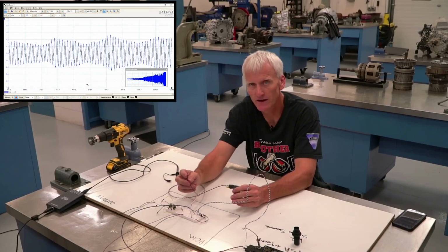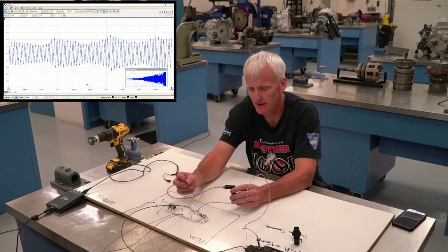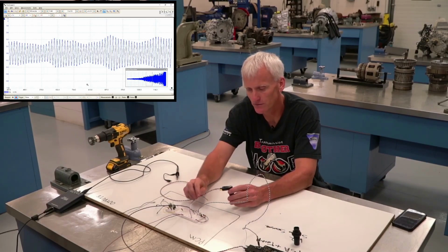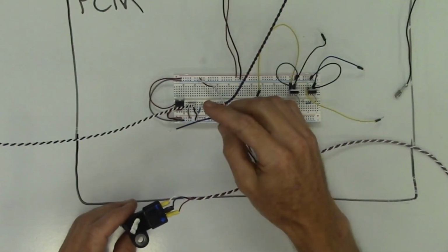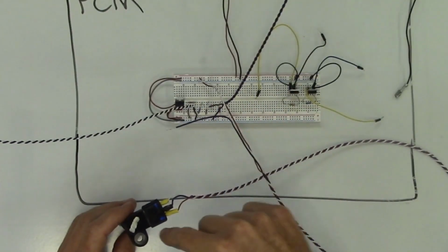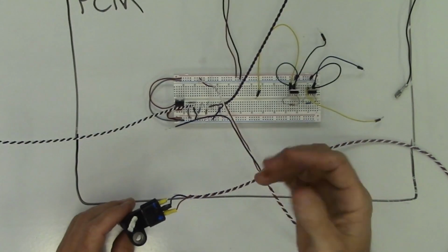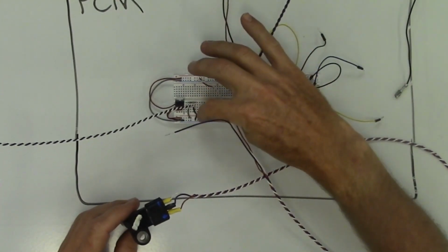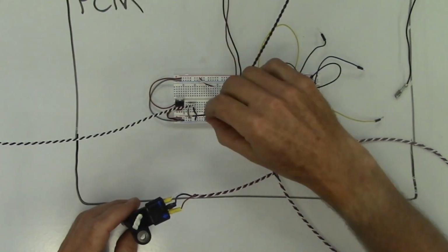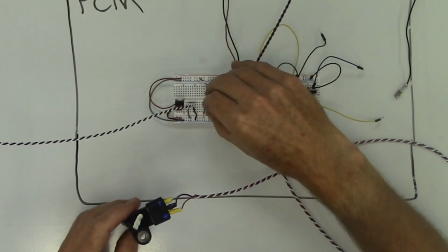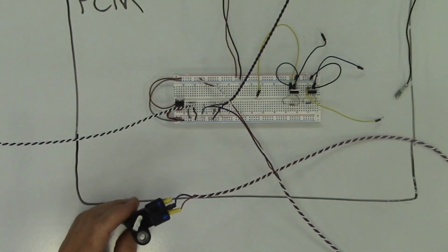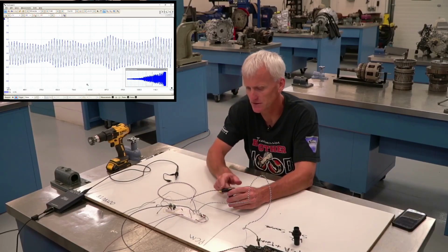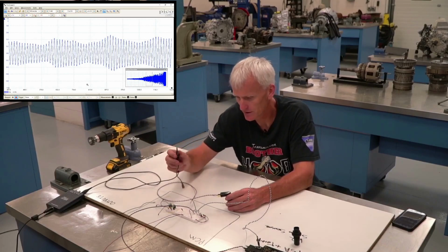So the computer is going to provide 5 volts, or 10 volts. The voltage that a Hall effect device works at could be different from different manufacturers, but we're just going to use our 5-volt output from our regulator. We're going to have it go through a resistor, because when it grounds out, we don't want to short out the 5-volt circuit. So I'll use this 100,000 ohm resistor right here, and you can see I've got power going in. So now I'm going to have 5 volts through a dropping resistor going to this circuit. I'm going to go ahead and hook up my scope to it.